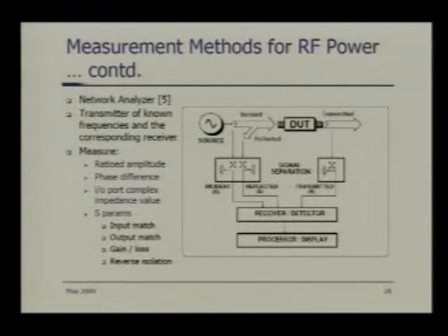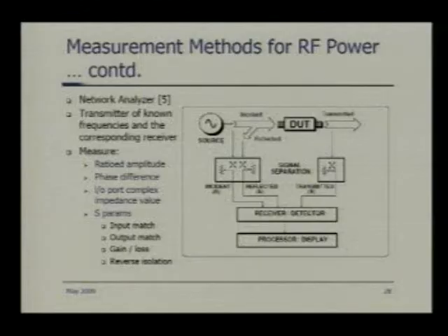There is another method that you can use for measuring the RF power, that is the network analyzer method. In the network analyzer method, you also apply an RF input. So basically you are sweeping the input spectrum of the RF waveform, and for every frequency in the frequency sweep, you are measuring the RF output response. Okay, so actually probably I'm not going to go through the detail. I see that it's becoming more and more complex.